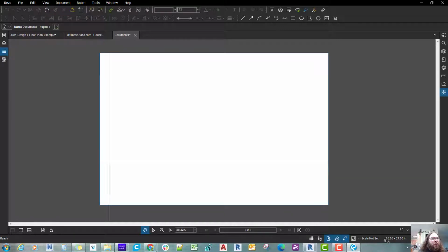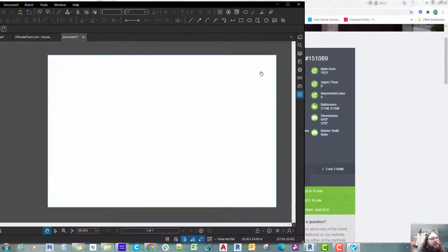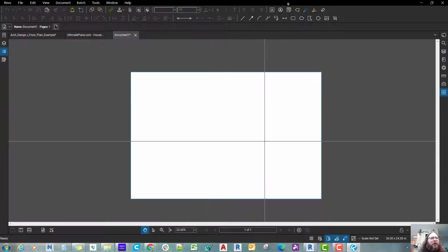When you're in the Bluebeam PDF, they have different profiles. I have a custom profile that I've done. Let's see, it's not showing up on the sheet, so let's bring it over here. So you can have a construction profile, advanced, where you get to choose the different toolbars and different items you have. Field issues, quantity takeoff. So if you were using this for getting square footages for a project, so that you could find out how much material you needed. You might want to play around with this, see what kind of settings there are, and I'll do a different video showing how to set that up as well. But just for now, we'll create our blank PDF.